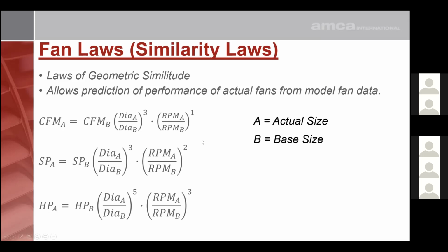We call them fan laws, but they apply equally well in pump applications. The only difference is that pumps typically handle incompressible fluid flow, and industrial fans are typically, but not always, compressible flow. The laws as detailed here don't include the compressibility coefficients, but in the AMCA 99 details, it's all spelled out quite clearly.